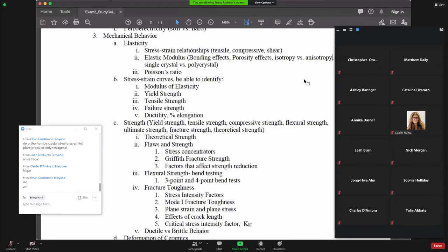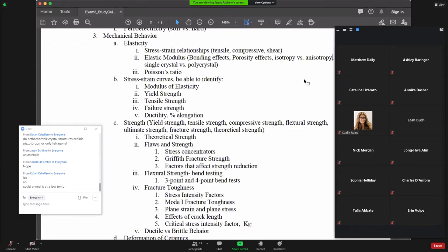Okay, so we have this sample. It has some larger diameter grain, and we want to make it smaller. So we start with these nice equiaxed, say 0.4 millimeter or 0.04 millimeter grains, whatever the problem said, and we want to make it smaller by a factor of 4. What are you going to do? Cold work it at room temperature and then anneal it at a higher temperature to get recrystallization. Perfect. This is awesome.